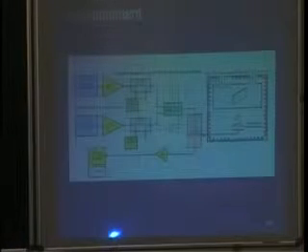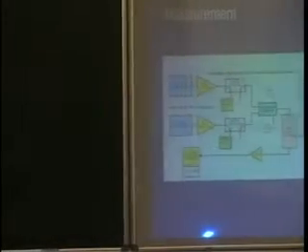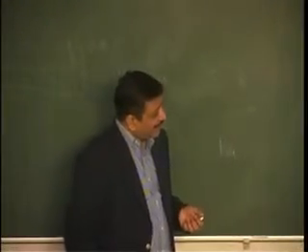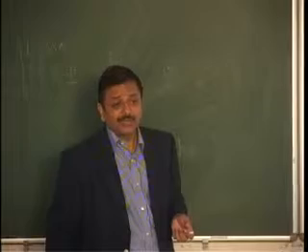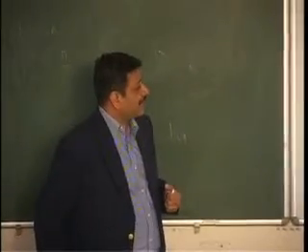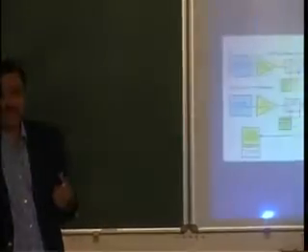Again, all these measurements are in radiation mode, so all the measurements have to be carried out in an anechoic chamber, which is nothing but a shielded room with absorbers, and you have to ensure that no other source of radiation is there. There are certain papers available where people have done a lot of work on AC ducts. Air conditioned ducts also give PIM generation, because there also you are using high power, and there may be some non-linear contact, and tunneling effects, and they propagate in the tunnels, and inside the chamber you start getting signals at different orders of frequency.